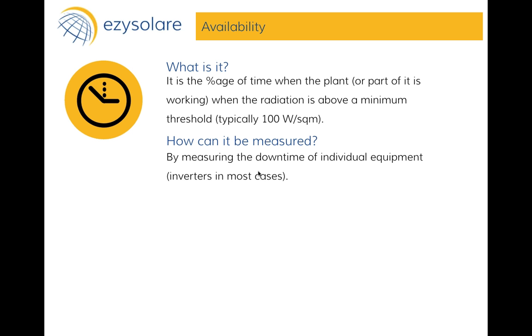The O&M contract value was 6 lakhs. So in case you compensate it by the same percentage that you lost in performance ratio, you end up getting about 16,800, which does not compensate you enough. So you can again probably have a 1% to 5% kind of a ratio, that for every 1% decrease in performance ratio, you'll have a 5% decrease in contract value of the O&M contractor. You still won't be able to recover enough, but that should serve as a large enough detriment to the O&M contractor. Right? So this is one of the other metrics, which is performance ratio.